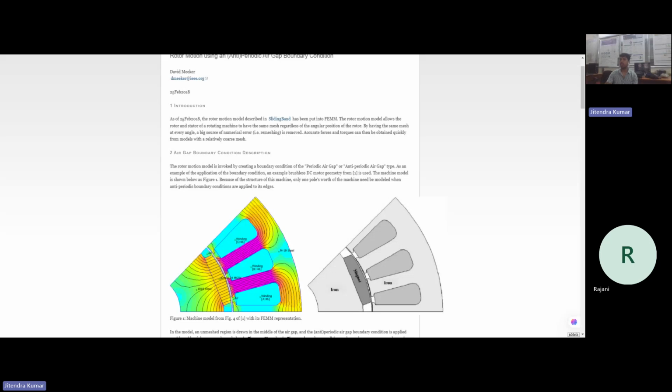Have you tried tweaking the windings, like giving the number of phases equal to one? What is happening is that in the winding part it is okay. If I give number of phases as one, it accepts. Then I went to the calculation part. I select passive generator because here it's not a motor condition, it's a generator condition.